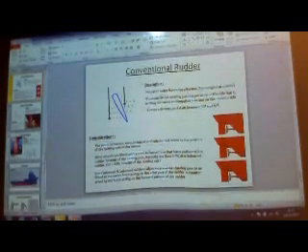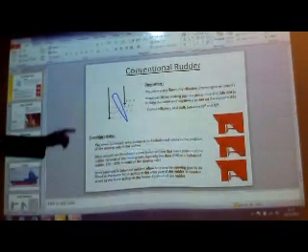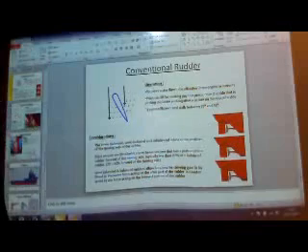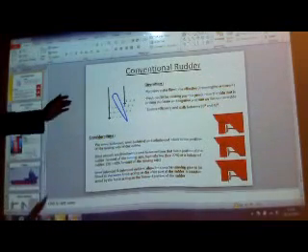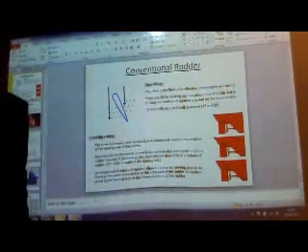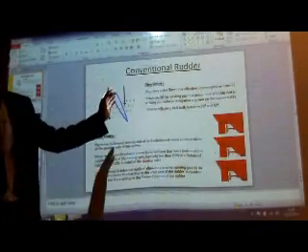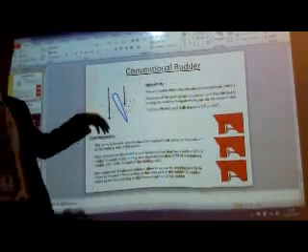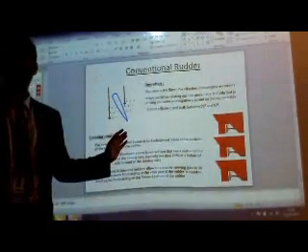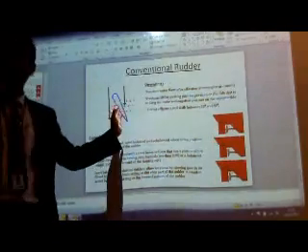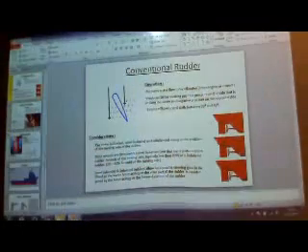Higher flow, higher lift. So when the velocity of water passing through it is higher, then even at a small angle you can create high lift. When the velocity of water flowing around it is less, then to create that same lift, you will need to give larger deflections.